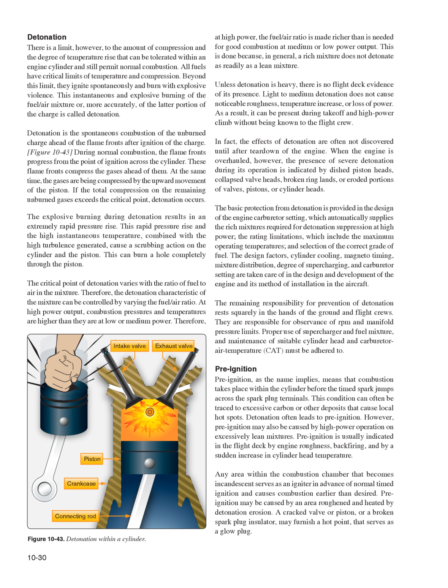Pre-ignition, as the name implies, means that combustion takes place within the cylinder before the time spark jumps across the spark plug terminals. This condition can often be traced to excessive carbon or other deposits that cause local hot spots. Detonation often leads to pre-ignition. However, pre-ignition may also be caused by high-power operation on excessively lean mixtures.